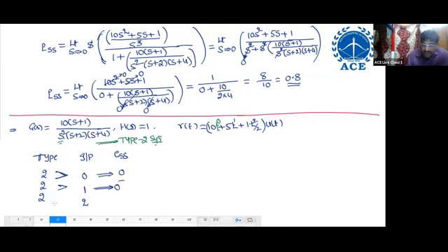Third is type equal to input. Type equal to input means the steady state error is A by K. What is A? The amplitude of the input. Which input? Input 2, which means parabolic. The parabolic input is A t squared by 2, so this is the standard form, and A is 1. K is the numerator constants by denominator constants.